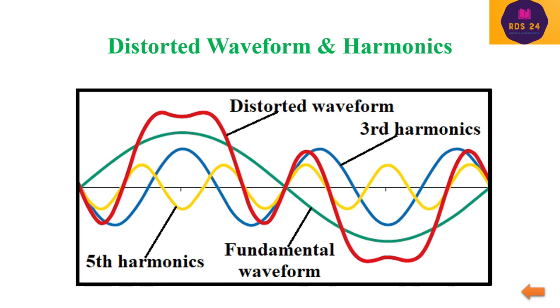Such as, if we have a frequency component of 150 Hertz, our reference frequency is 50 Hertz, but we have some content of 150 Hertz in our voltage or current waveform, then it will be considered a harmonic part. 300 Hertz, 400, 500, 550, 1000, 2000, these are some harmonics in our waveform, but the magnitude of these harmonics is very small as compared to the fundamental.